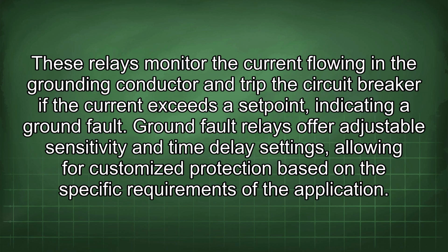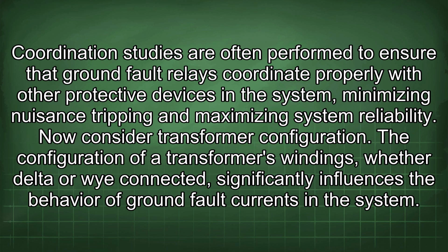Ground fault relays offer adjustable sensitivity and time delay settings, allowing for customized protection based on the specific requirements of the application. Coordination studies are often performed to ensure that ground fault relays coordinate properly with other protective devices in the system, minimizing nuisance tripping and maximizing system reliability.